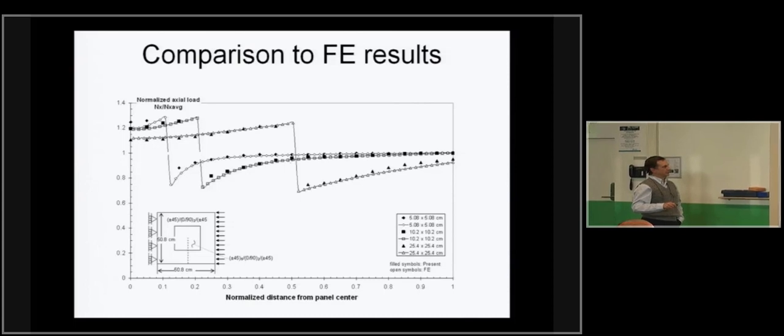The center square is here, and I'm plotting the nx, or the stress. If I divide nx by the plate thickness, that would give me the sigma x stress, on a transverse line, transverse to the load applied, from the center all the way to the edge. And I get 3 types of curves for the 3 sizes of the squares that we said we are using.